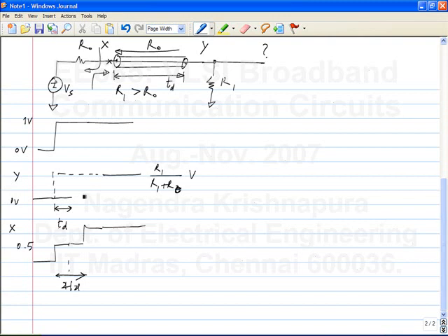I mean, I don't know, you tell me. No, incident voltage is half a volt. Okay. And the reflected voltage is, it will be just half a volt, or it will be this voltage, R0 by R1 plus R0, or R1 by R1 plus R0. It should be, right? In this case, it will be. So there are no multiple reflections in this case. Yeah, that's right. I mean, nothing comes back after TD in this case.